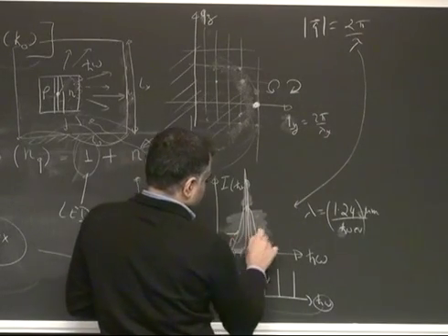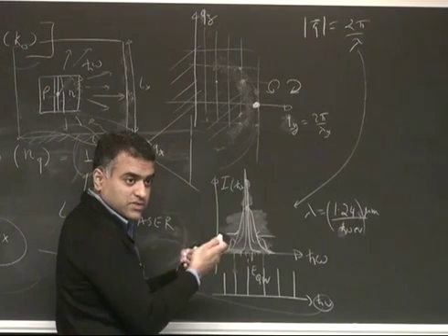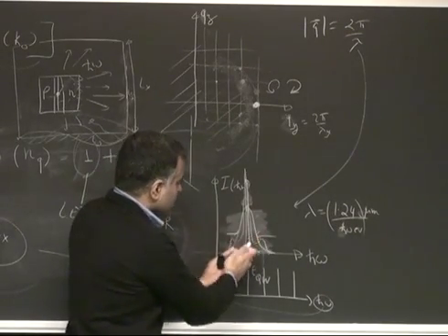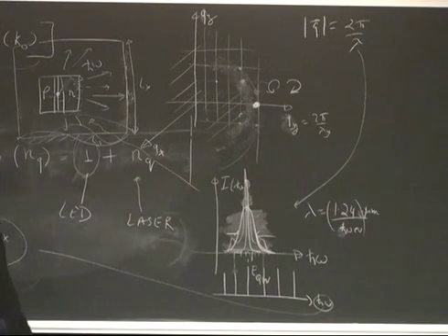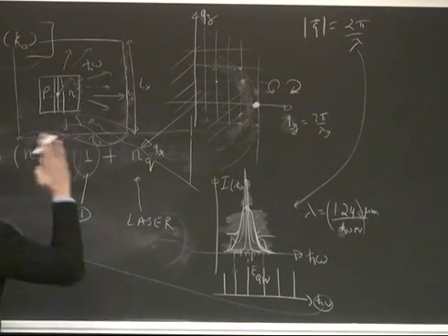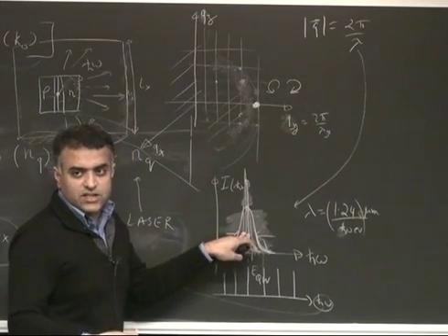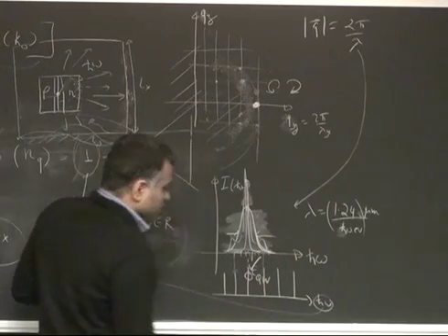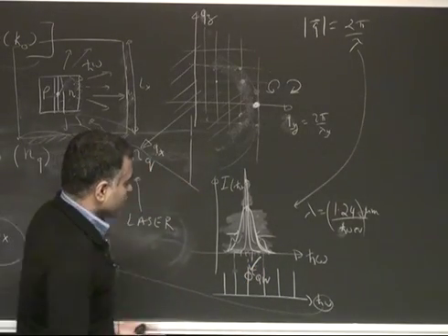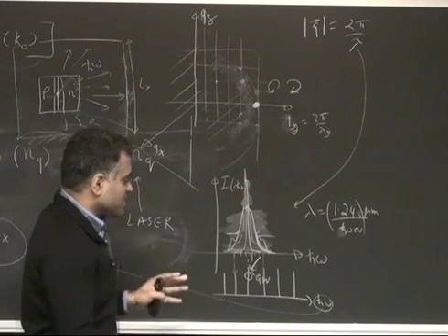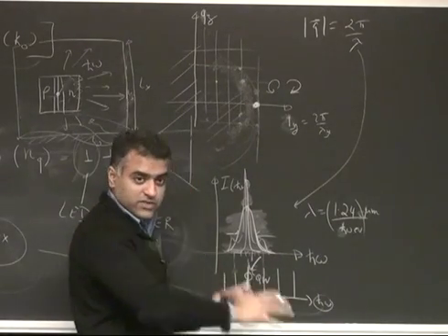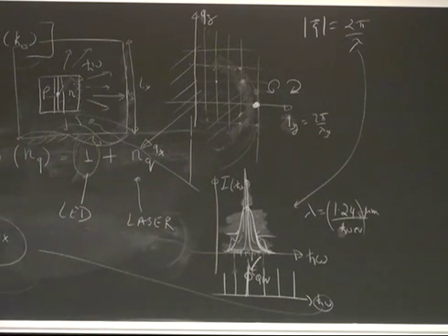So the width of the spectrum, as you measure the luminescence, really narrows. It goes into one. In the process of going from a broad spontaneous emission spectrum to the stimulated emission spectrum with one peak, there's quite a bit of nonlinear dynamics. The dominant mode gets into a very nonlinear regime. If it was a linear process, every mode would have its equal share and just keep going up like that. But the moment this nonlinear aspect kicks in, this mode sucks out all the energy from other modes and just dominates. That's what happens in a real laser. You saw people solve rate equations to see that process.